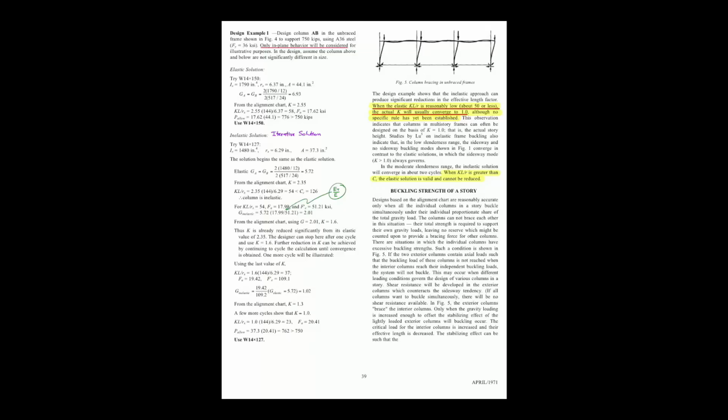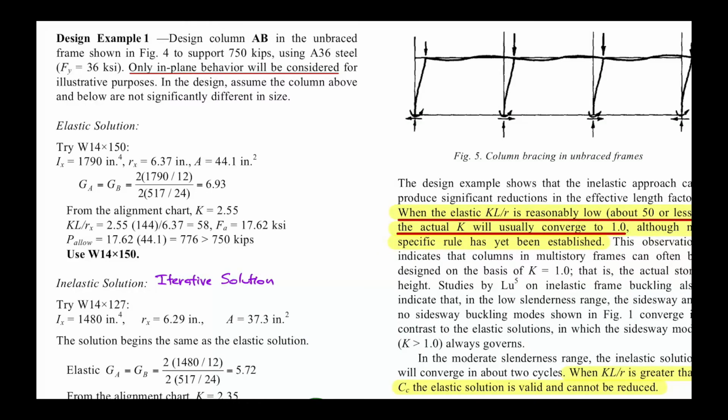Then this is for the beam, which is already given in the drawings, and this is for the A. You have two columns, right? For the beam, you also have two beams. EI over L, this is your L, the length. Turns out you get the ratio 6.93 for both top and bottom.